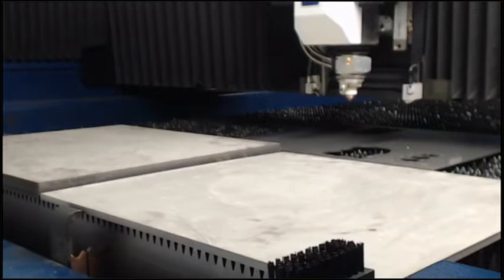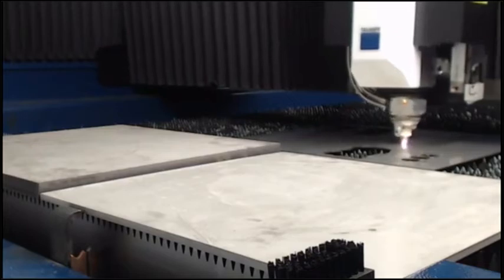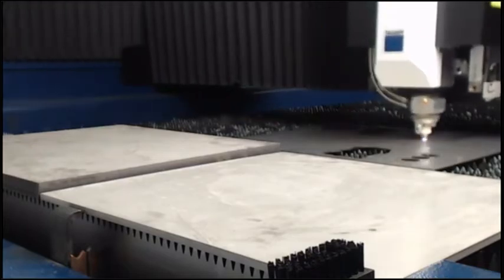All right, guys, we're all set up and ready here. So this is going to be, again, 1/8" stainless steel with compressed air now. This is going to be actually a little bit faster. This is going to be 1,106 inches per minute. That's actually pretty substantial. You'll see it do a nice etch there.